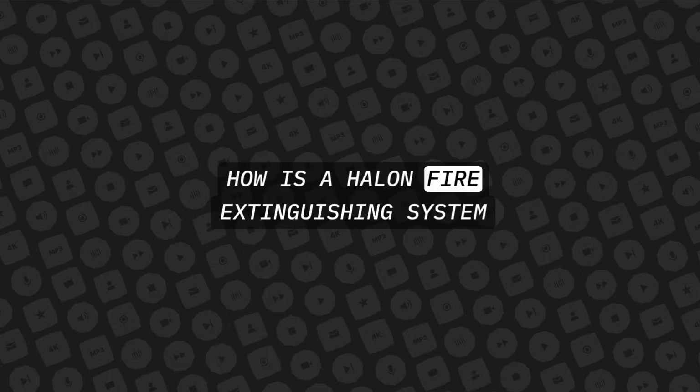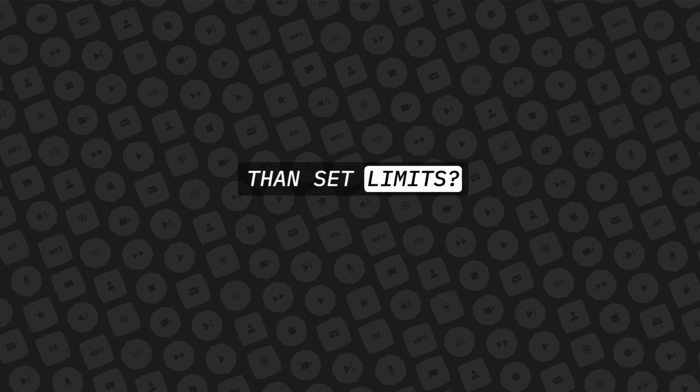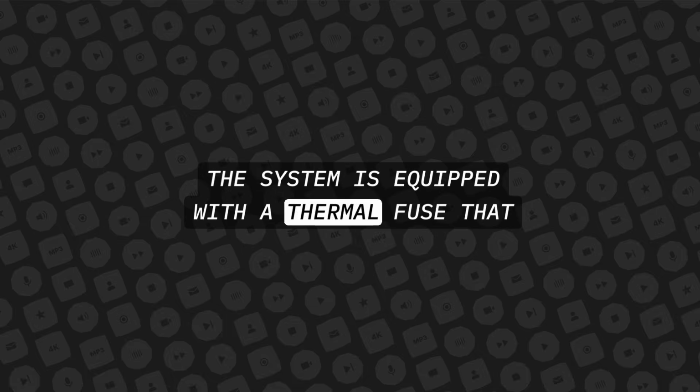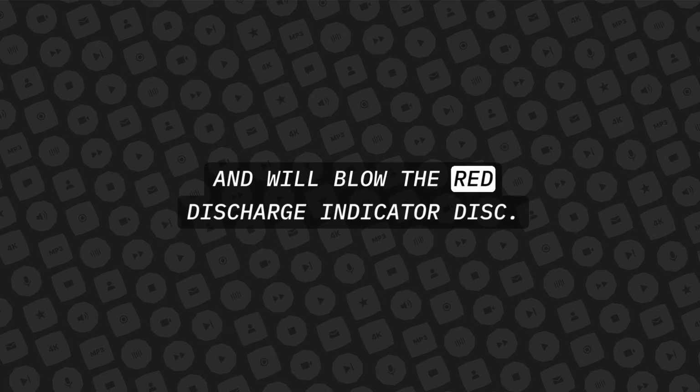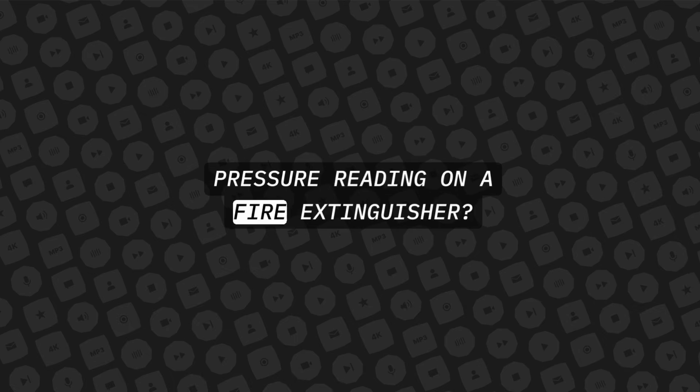How is a halon fire extinguishing system protected from temperature rises more than set limits? The system is equipped with a thermal fuse that will melt at high temperature conditions and will blow the red discharge indicator disc. How does ambient temperature affect the pressure reading on a fire extinguisher?